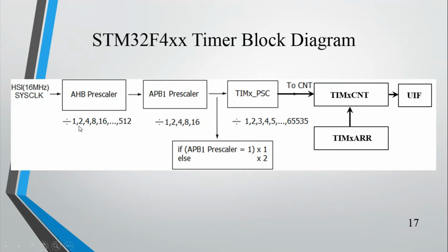Again, for this prescaler ratio also, if you configure it as 2, the total delay will again be multiplied by 2. That means the time delay that can be generated by the timer will be multiplied by 2, again into 2, again into 2, because you have configured these 3 prescalers as 1:2. So this is how the prescaler works. If you want to generate a delay more than is possible by the normal timer counter, you can configure the prescalers appropriately.